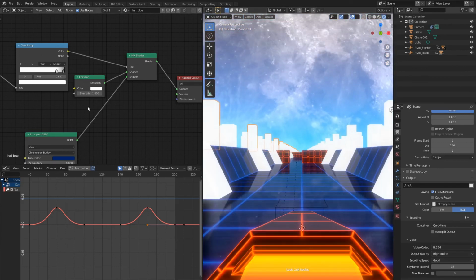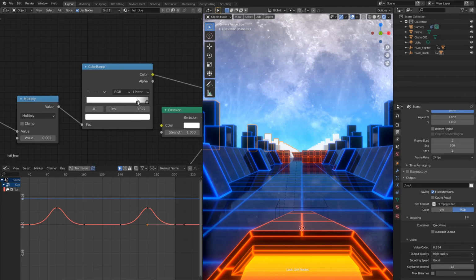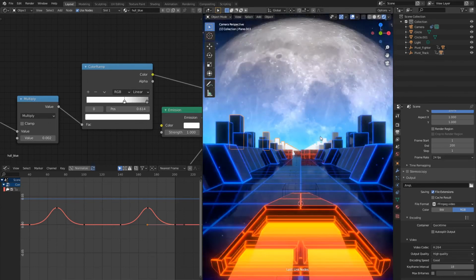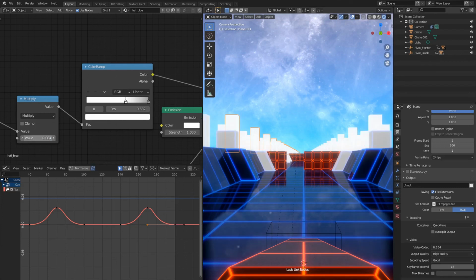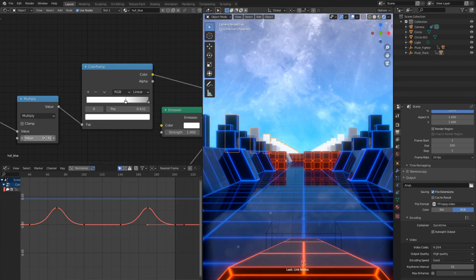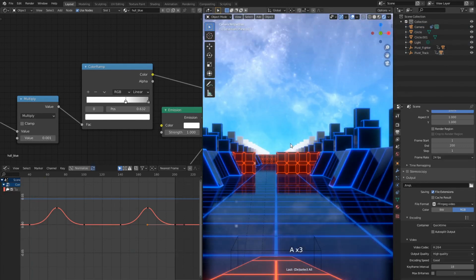Everything looks white. Let's adjust Z depth multiplication factor to move fade border away from the camera. I'll start with a really small value like 0.002, and now we can drag this gradient slider to fine-tune fade out distance. The closer I move it to the dark point, the sharper fade out becomes. Perhaps I should try other multipliers, it seems too close to the camera. 0.004 is too strong. 0.0015 seems too, let's try just 0.001. Okay, now it starts fading out exactly where I want it.